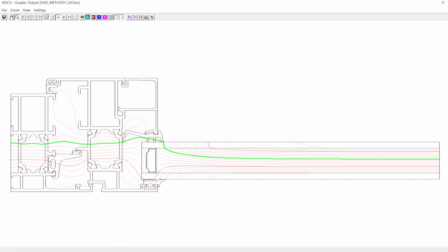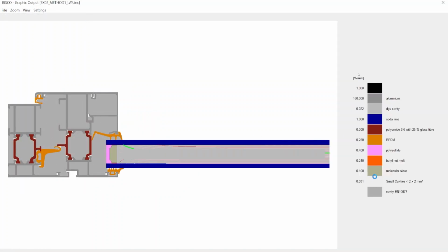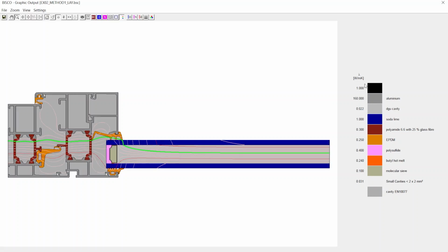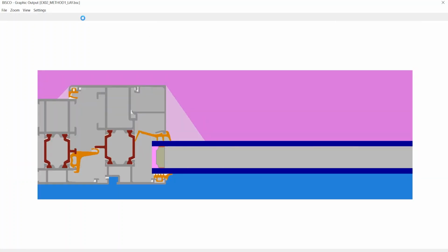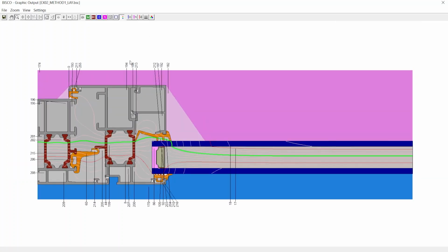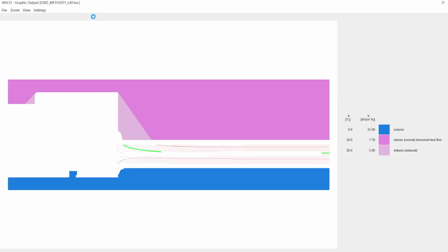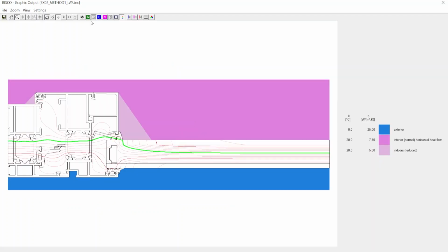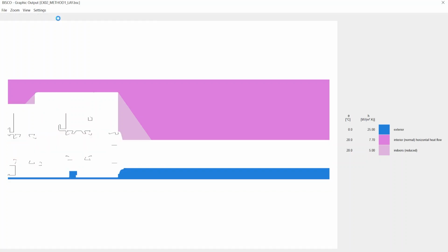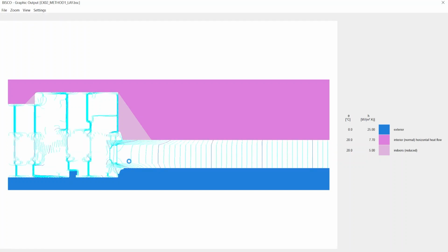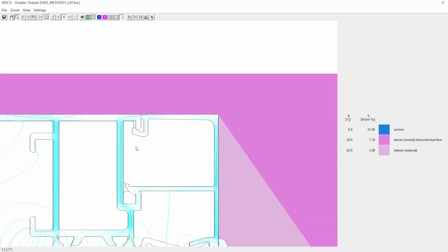You can also fill with a material preview where you see conductivities in ascending order at the index for each material. Fill with bitmap if you want to see the material colors along with all colors labeled. If you choose Fill BC, only boundary conditions will be filled. You can turn on heat flow lines and turn off isothermal lines to visualize heat flux.